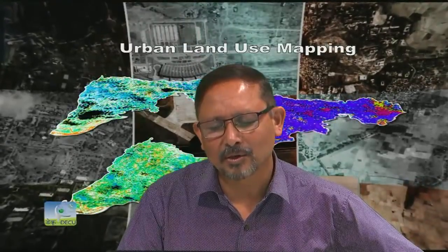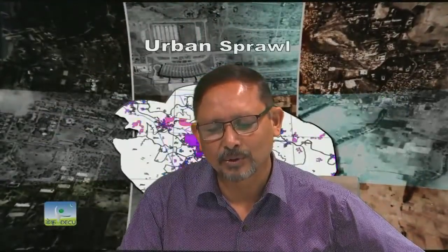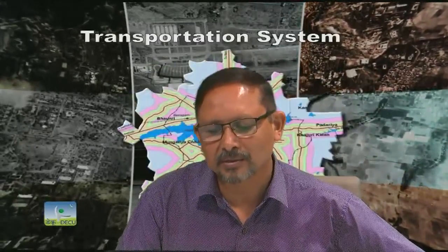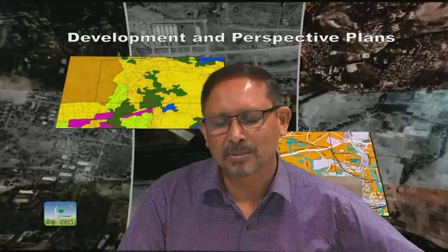How can you calculate slope? It is very easy. If you take the DEM and put it as an input into the hydrological processing software, there is a direct option. You can generate the slope map. Otherwise, the formula that this algorithm uses, I have shown you there. Different software algorithms are written to calculate the slope for each pixel.